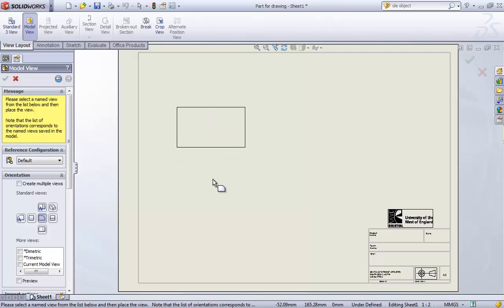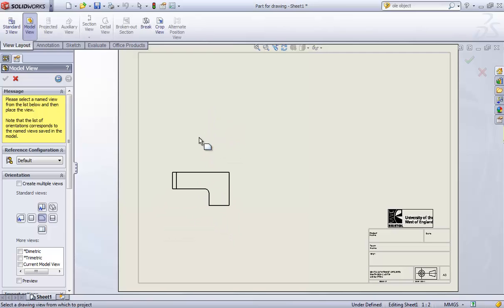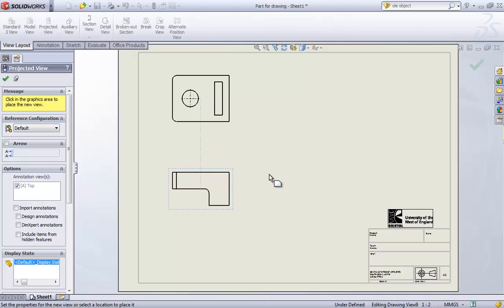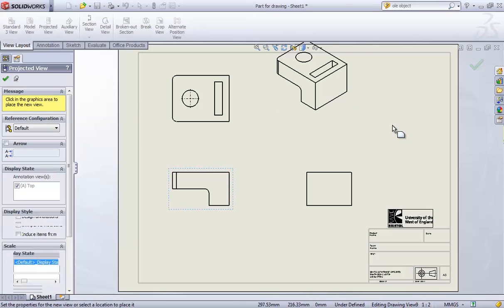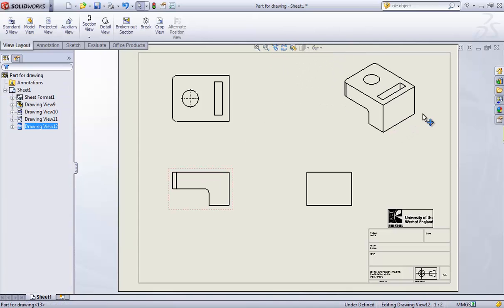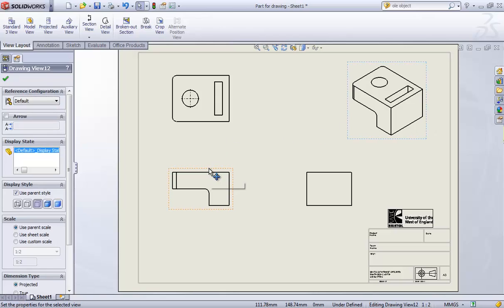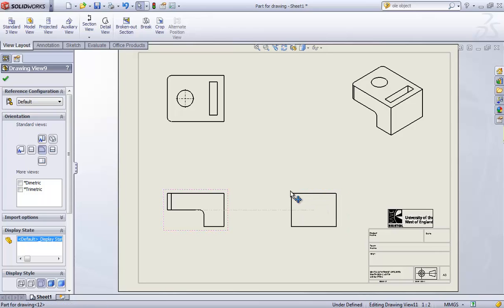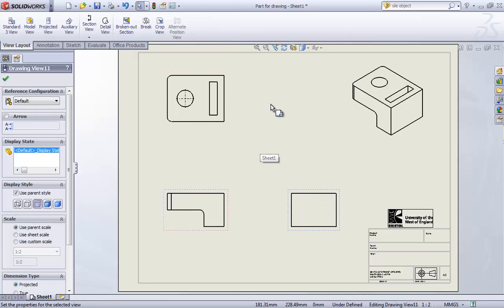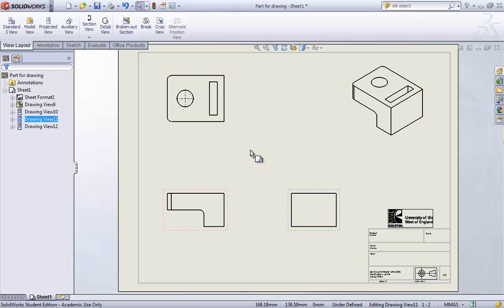Okay, so as I said earlier, I'm going to go with the front view here, my top view over here, right hand side view here, and then isometric view somewhere over here in the space. And as you know, we can reposition these as and when needed. So this was maybe the third most important step, to bring in the views, and bring in the appropriate views, not just any random views. Bring in something which is doing justice to your drawing, which is most important to communicate all the ideas and all the dimensions about the part.